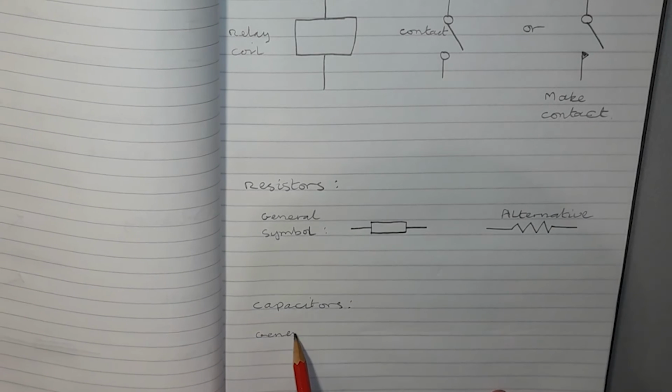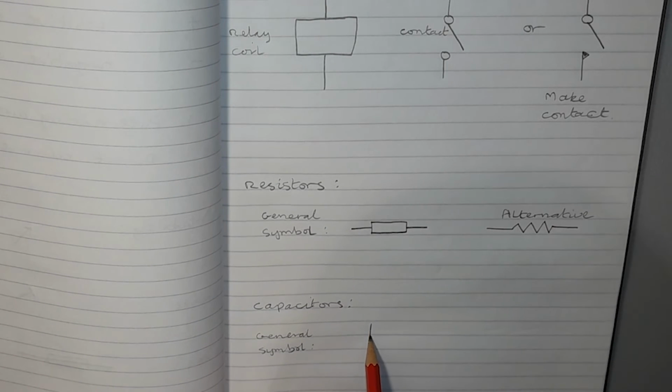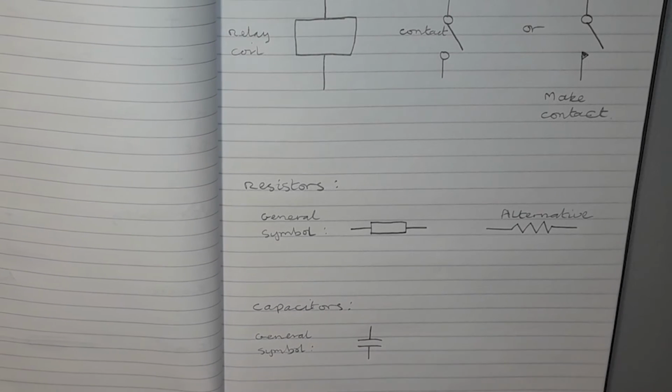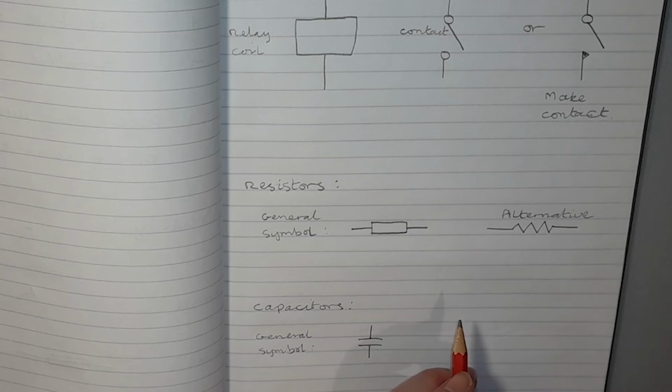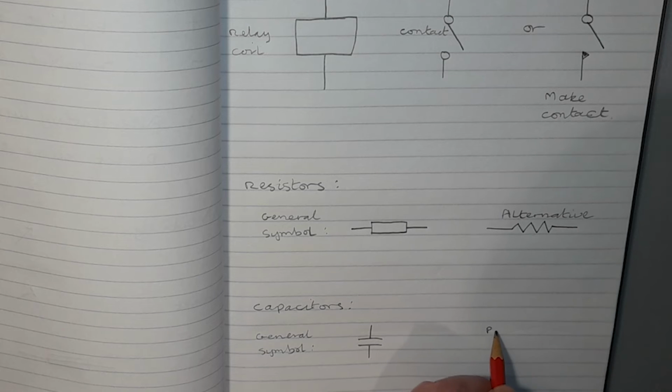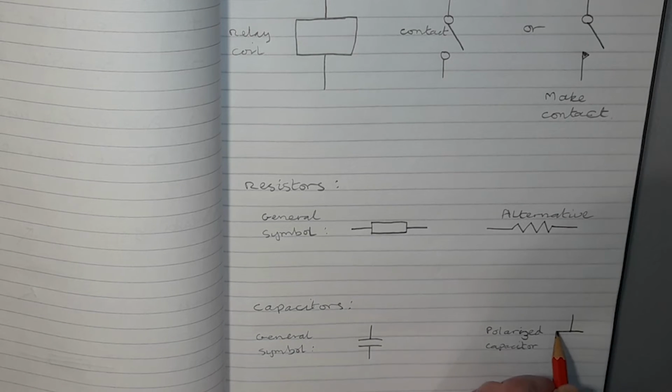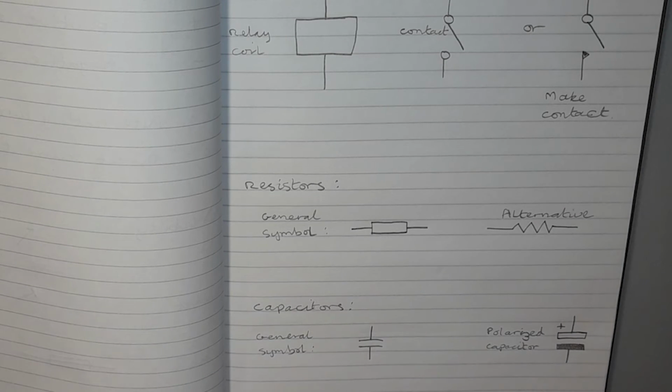Capacitors store electricity as an electric charge, much in the same way as you might understand static electricity. The symbol represents two metal plates, which is exactly how it is constructed inside, or more precisely, two very thin metal foils rolled up together with an insulator between them.